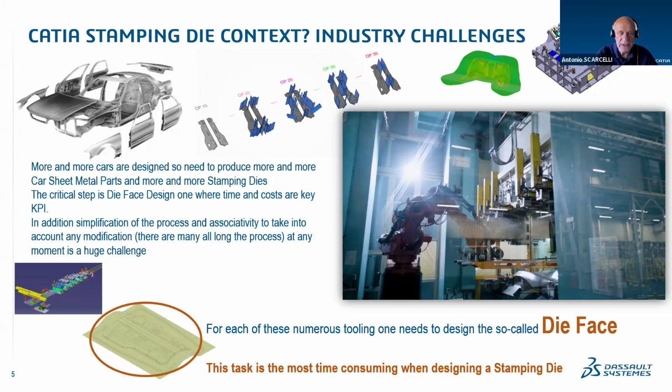How will I design the process to produce my dedicated part, and how will I be able to define the different elements, surfaces, curves, direction of stamping, direction for the cam, to give this information to the person that will do the die design, to the person that will do the die manufacturing, the die machining, and so on.